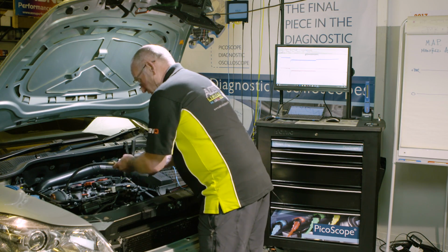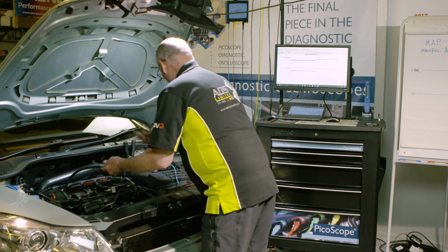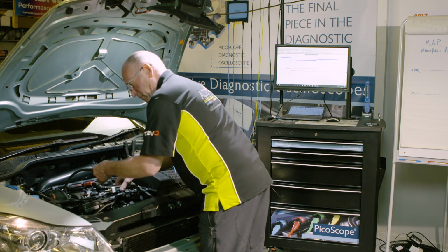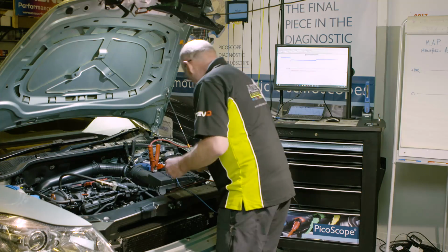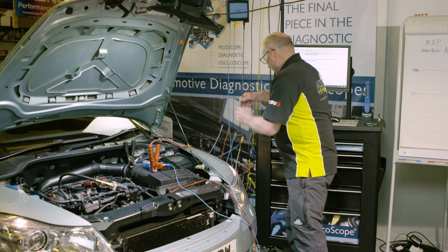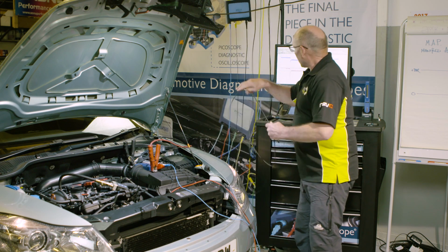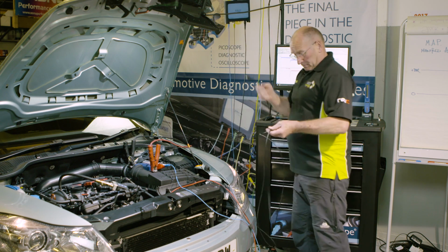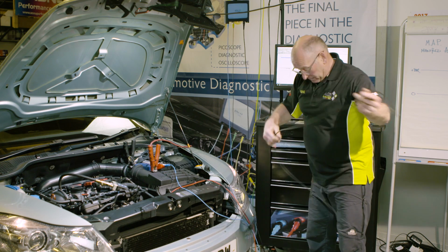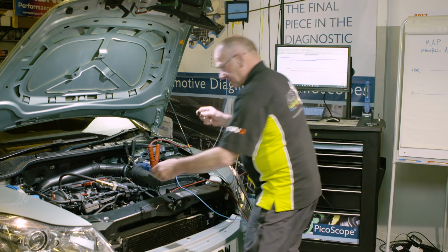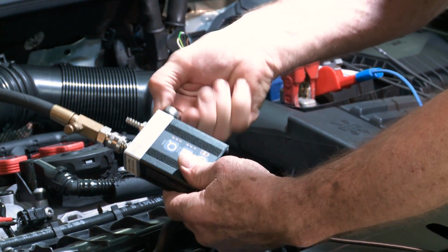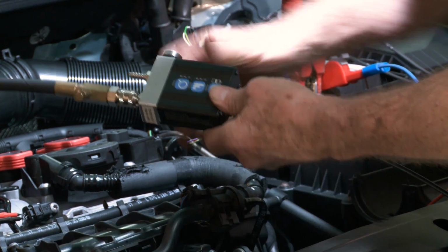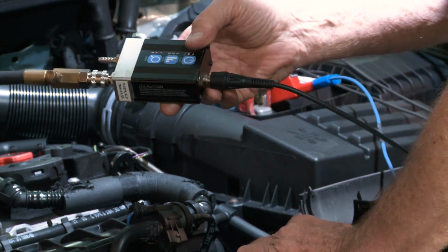Now, I'm not intending to introduce that poor compression. I think we've proven that part conclusively in what we've just done, but put the WPS in the cylinder, connect the BNC lead, and it's on the 4th channel. I've adjusted the colour to black from yellow. I find it's a stronger colour. Let me close the bleed device so there's no leakage. There's no one-way valve in this device, so we're seeing